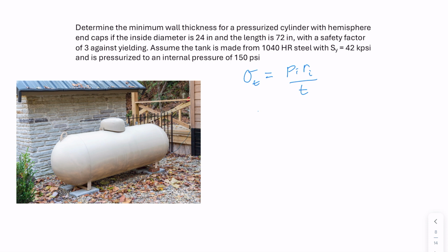And so often we just go with this assumption because you will also see, like in the Shigley book, for example, that the stress would be the pressure times the inside diameter plus the thickness, all over 2t. And this is very close to that first equation with the average stress. So quite often when we're doing a pressure vessel, we usually have a higher safety factor, so we're fairly safe using this average tangential stress, and that's what I'm going to use here.